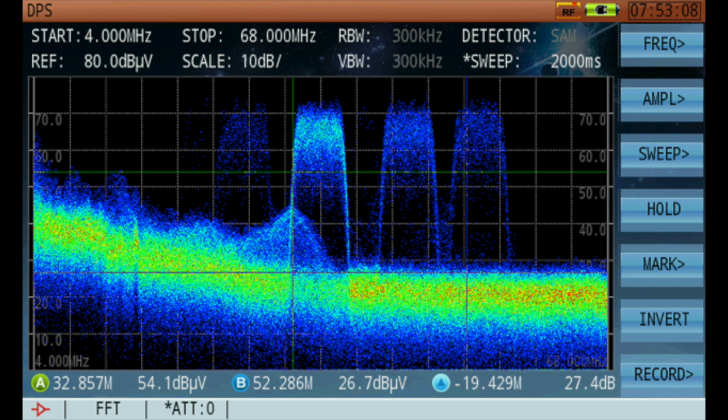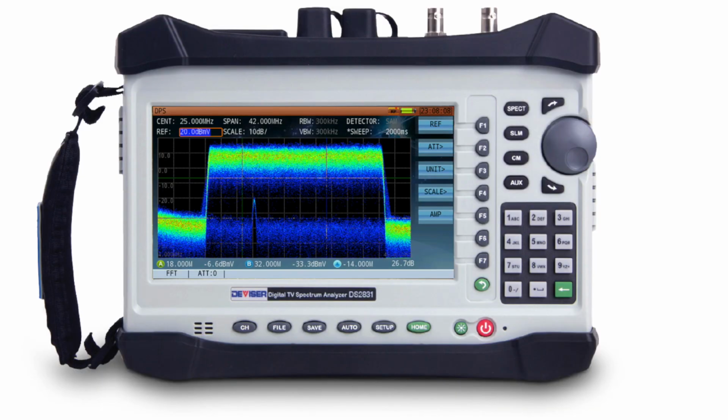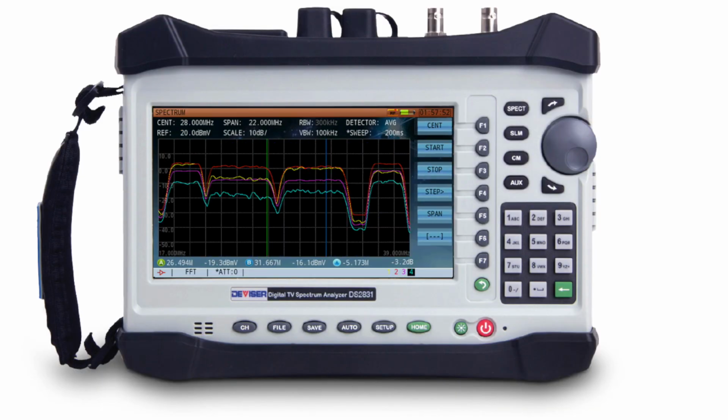This picture represents a DOCSIS 3.0 upstream transmission and clearly shows what the differences in signal presence make. The colors assigned to bitmaps across the capture bands are hotter as more signal presence is detected. Up to 200 MHz can be set to capture in this mode. We cannot say enough about the importance of having both the DPS function and a true spectrum analyzer, which will provide the ability to view much deeper into the CATV network.